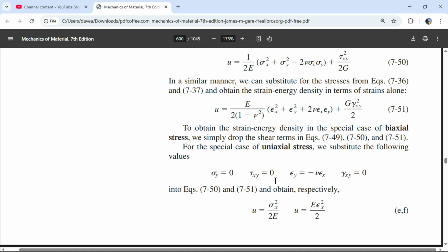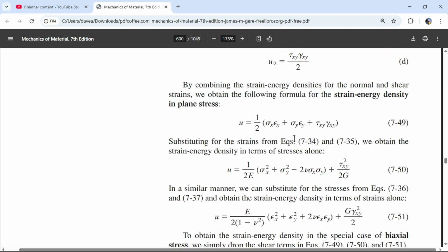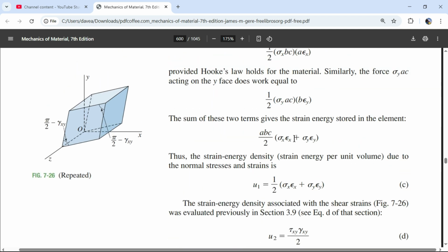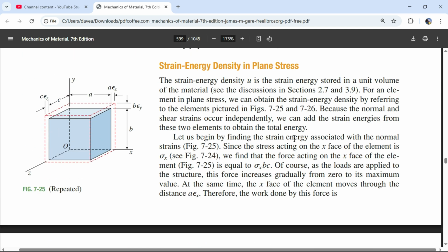Okay, so we are just having our stresses in the x direction, so that means we for sure know our strain is just Poisson's ratio times the stress in the x. And then the shear is 0, the shear angle is 0, sigma y is 0, and this is just a function of the strain in the x and the strain in the y. This is not a function of the strain in the z direction. I did not realize that. And so why is that the case? That's fascinating, that caught me off guard.